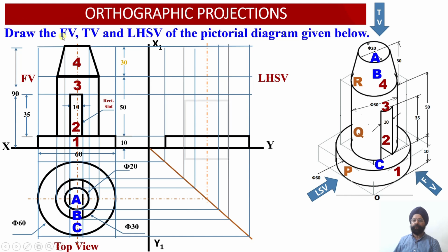Now the cylindrical portion we can draw. Again we have the cylindrical portion, but now the slot is not visible to us straight away. There is a slot which is running perpendicular to this left side view dimension, or the direction of viewing. So here no slot will be available as such. Rather, this slot is running across this cross section, perpendicular to it. So this portion should be drawn as a dotted portion.